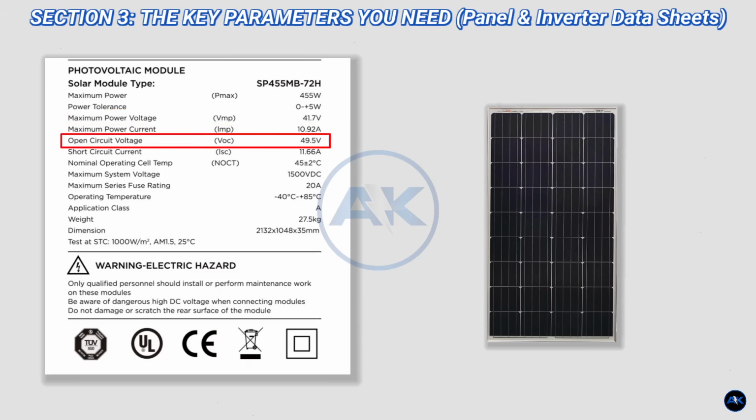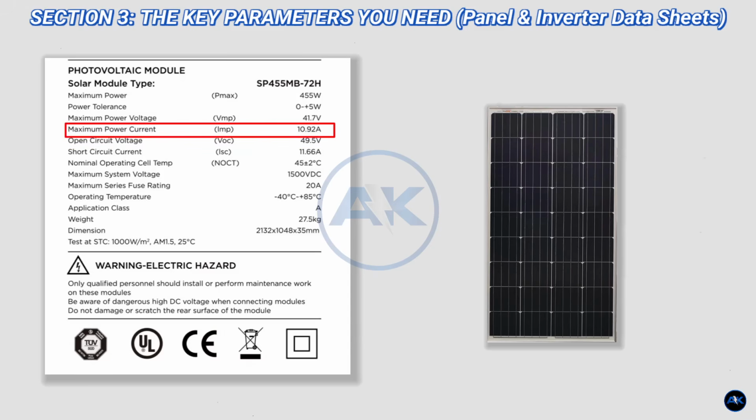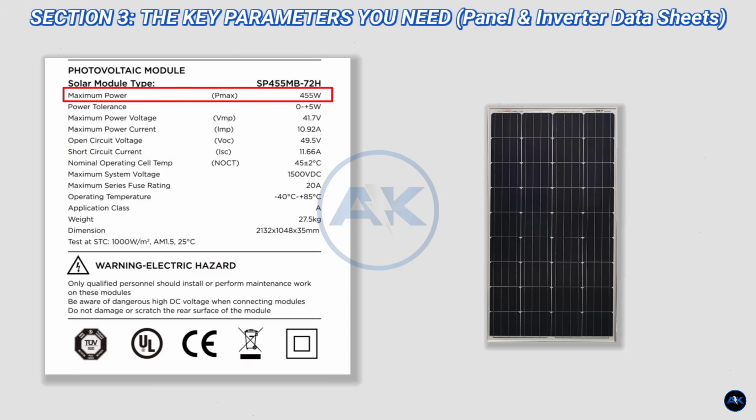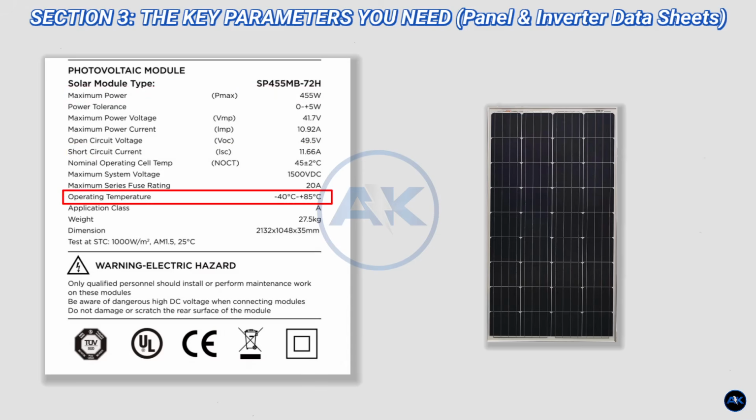This is crucial for checking the maximum string voltage. IMP, current at maximum power, the current where the panel produces its most power. ISC, short circuit current, the maximum current the panel can produce when its terminals are shorted. Pmax, maximum power, the rated wattage of the panel, e.g. 400 watts. Temperature coefficients, VOC, VMP, ISC.